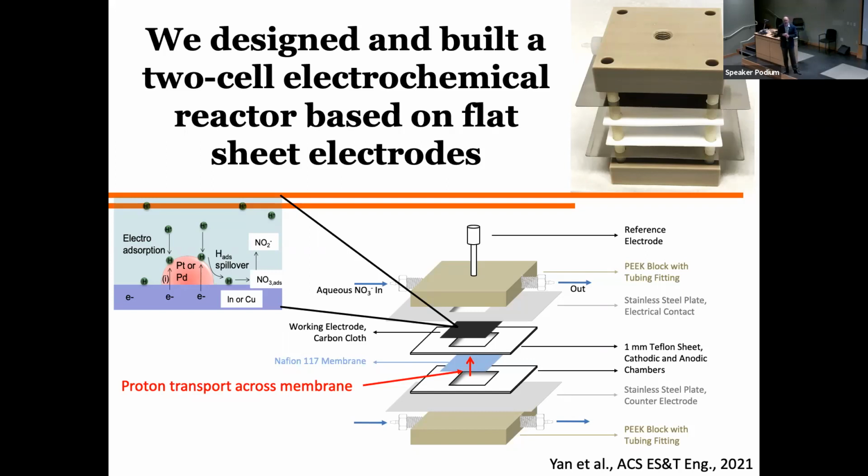In order to get sufficient reaction times, with our estimates of the intrinsic reactivity happening on the cathodic surface, I estimate that you need something that's about 2 meters by 2 meters by about, I think it's maybe 10 centimeters thick. All right, so it's a much larger system. And so are you going to get sufficiently rapid mass transfer across that Nafion membrane? I don't know. You have to have turbulent flow in those systems.